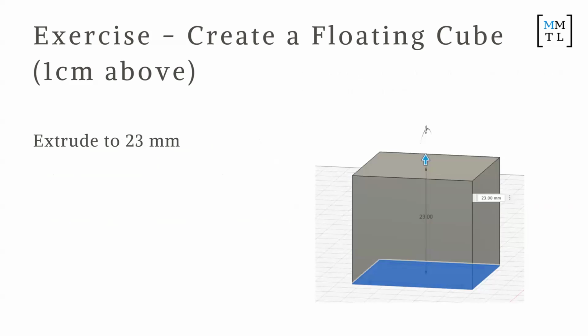If you want to extrude 23 millimeters, nice, that's good. Go back to your sketch, the sketch with the sort of cube on top. You can select the edge on your sketch. Yeah, try this one.